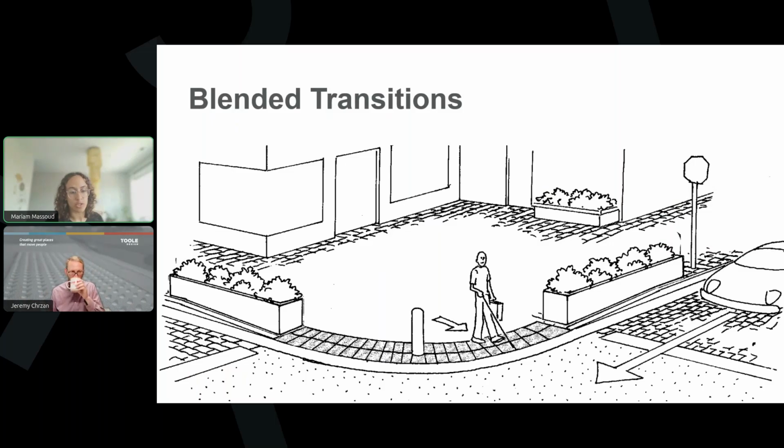So one approach that you could consider is introducing a short median or section of curb where the bollard is in this picture. So this could be 2 to 3 inches tall. And it would help not just with the vehicle encroachment issue, but it would also help pedestrians to orient themselves to the crosswalk that they're trying to use.